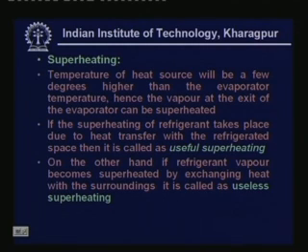On the other hand, if the heat transfer is taking place outside the refrigerated compartment, let us say it is exchanging heat with surrounding air, then you do not get any benefit. The refrigerant gets superheated, but you are not getting any benefit. This kind of superheat is known as useless superheating. As I said, if refrigerant vapor becomes superheated by exchanging heat with the surroundings, it is called useless superheating.